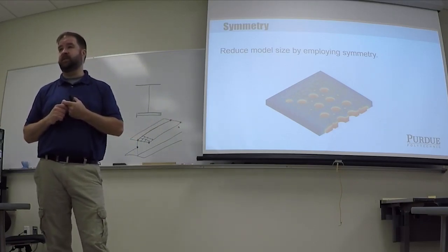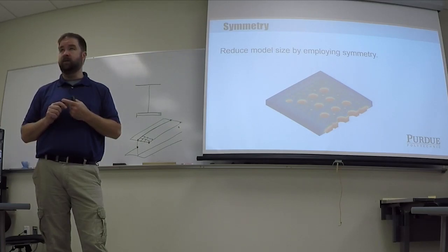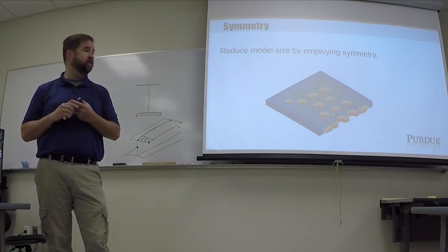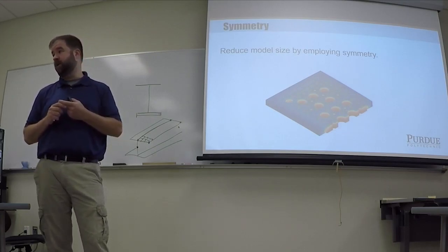All right. One other thing I wanted to mention real quick. Think about using symmetry to save yourself some work. And we'll talk more about this later, but I wanted to bring it up now. There is absolutely no reason to model an entire structure if I can simplify it by dividing it in half.